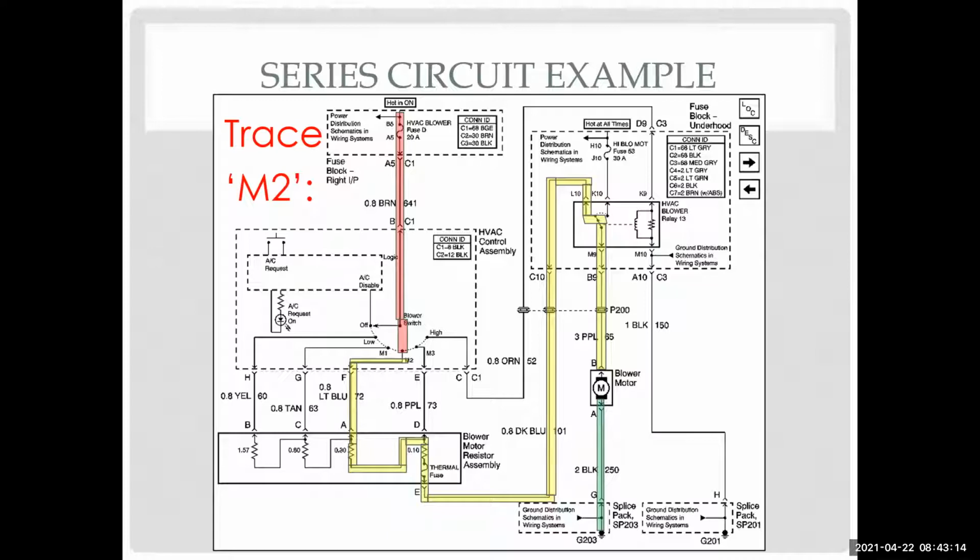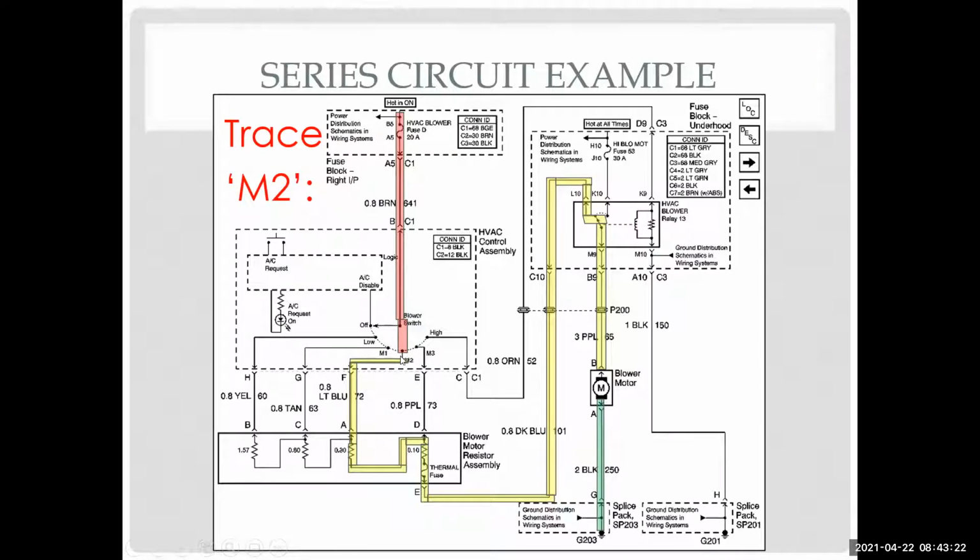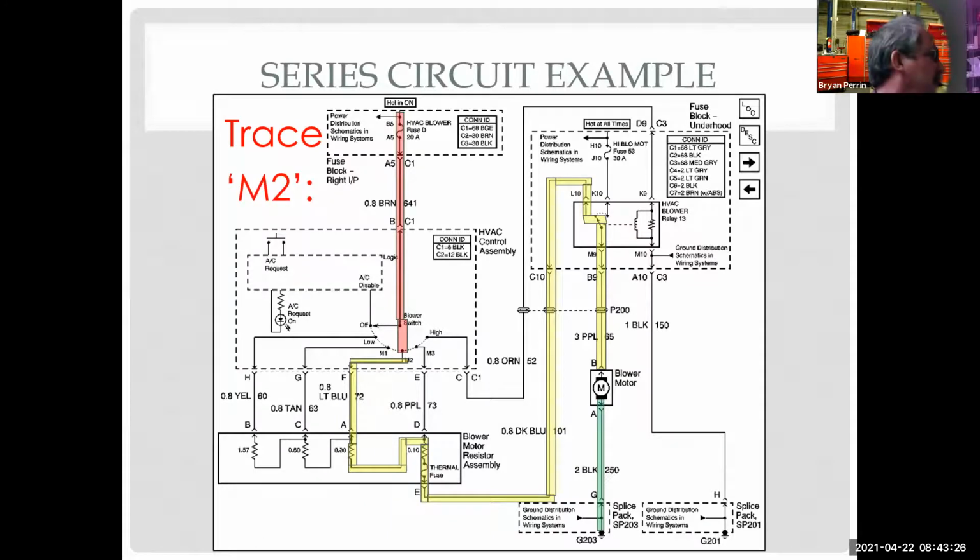Brian: So the only power source is where the switch is connected? Right, that's exactly why there's no power on the rest of these figures. You're correct. On the rotary switch, the only place power is going through is where the switch is touching, in this case, M2. So all these other ones aren't touching anything. They're just there. So they're an open circuit.